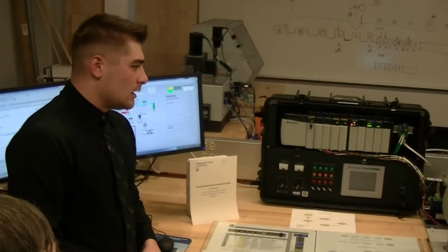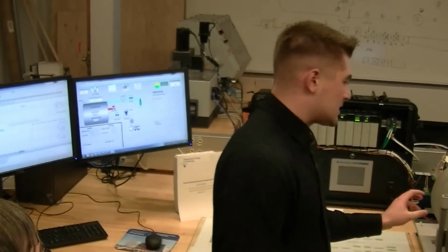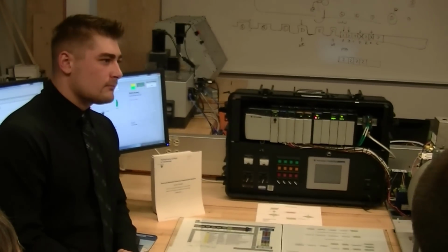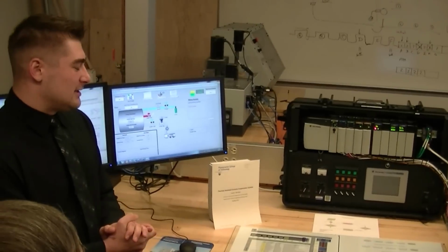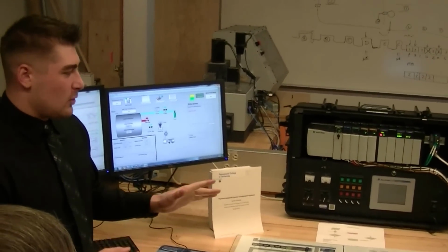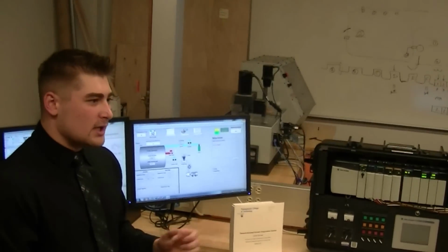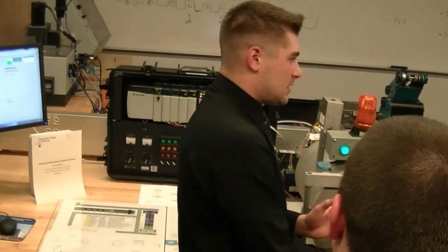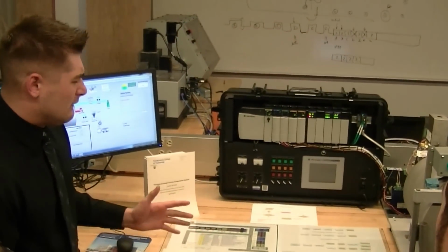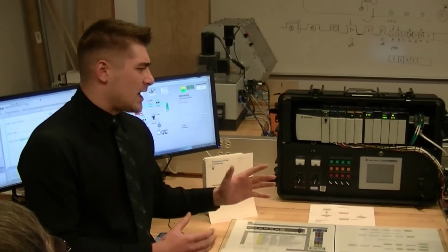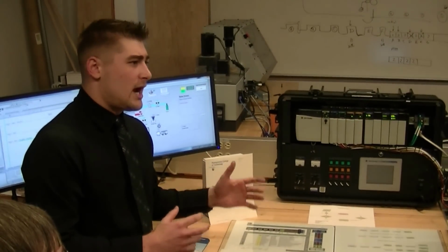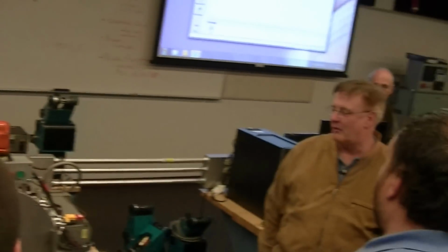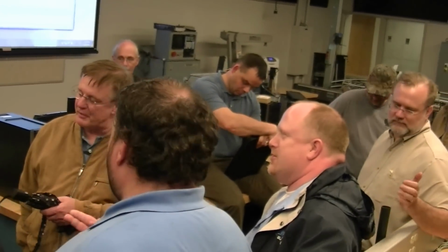Is it done to code? Well, in terms of the thickness of the walls, yes. Pressure vessels need to follow the ASME code. They also have an OSHA specification for pressure vessels. That's the one thing I don't have on here, what's called a relief port. They typically have that mounted on the top of the door, and it's a spring-mounted mechanism that expands out if there's an overpressure condition. If I'm not mistaken, it has to be 27% of the actual volume of the chamber. So at any given moment, if it does crack, enough of that's going to go out to vent whatever hazardous chemicals are in there. It either has to be a pressure release valve or a rupture disc.